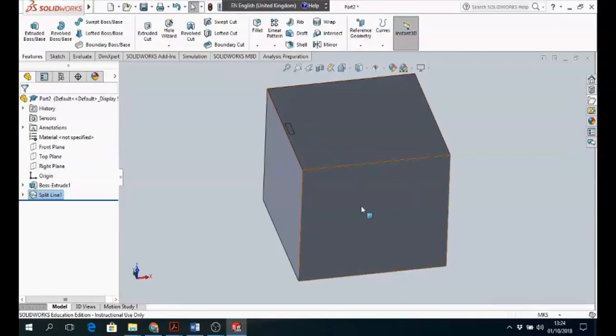So next up, on this wall beside it, we want to put both a window and an outlet down here. So that'll be 2 rectangles, each of which are about 1.5 high by 1 meter wide. So if we select our plane here, I'm going to do it on this plane and project it onto this face here.